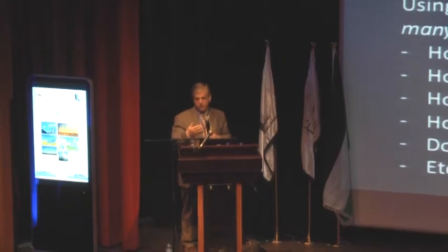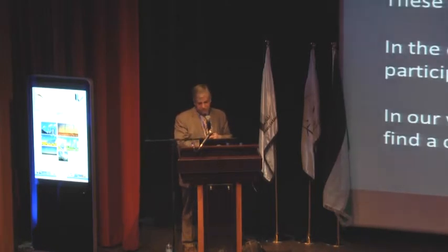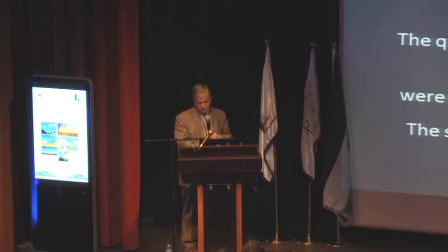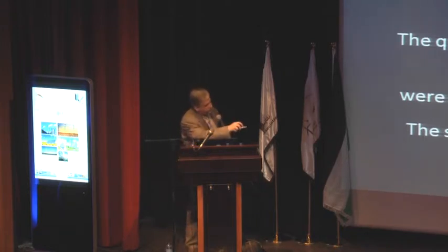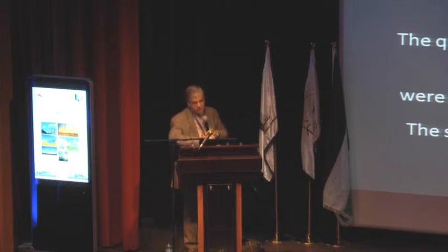And the kind of questions that people ask are, how much does a mode participate in the state? How much does the state participate in the mode? And this started in 1980-81 with the introduction of these quantities, the pki, that they call the participation factors. pki is the left eigenvector Li, its kth component, times the kth component of the right eigenvector. They called that the participation of the ith mode in the kth state. And they had an analysis of how they got there, which is based on choosing a particular initial condition. And that's been used.